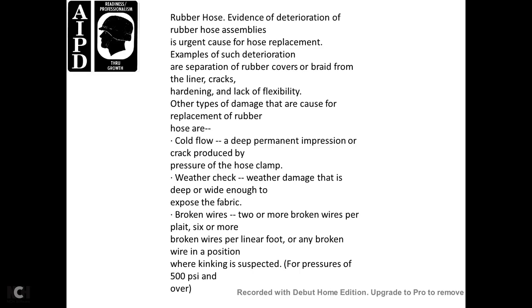Weather damage that is deep or wide enough to expose the fabric, and broken wires: two or more broken wires per plait, six or more broken wires per linear foot, or any broken wire in a position where kinking is suspected, for pressures of 500 psi and over.